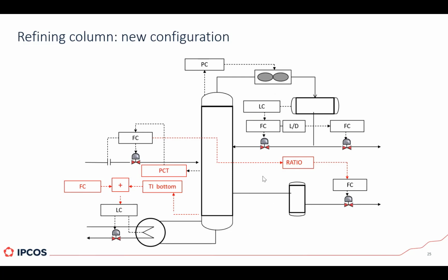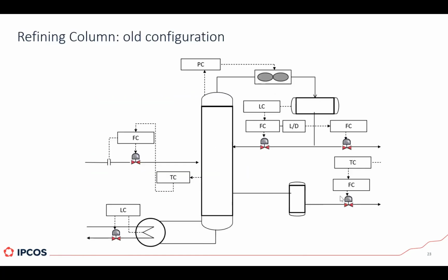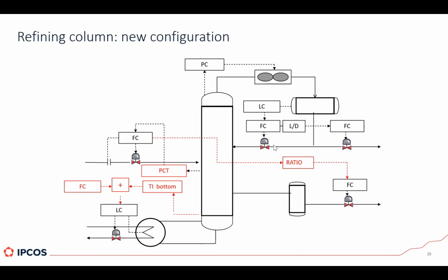Of course, that ratio can be changed in case you need a little bit more of side drop product, just because you're seeing that your impurities are increasing somewhere. But this is much better than the previous strategy. The previous strategy was based on measuring after and then acting. This ratio strategy gives you a lot more anticipation of what can happen. So it has proven to work, and it has worked there for many years, over 10 years.